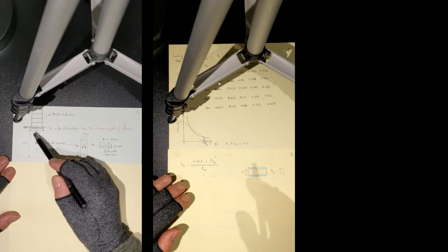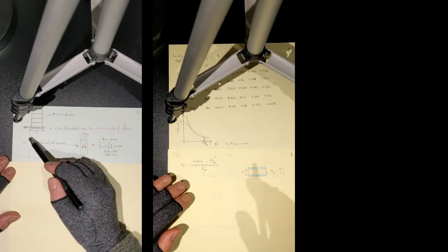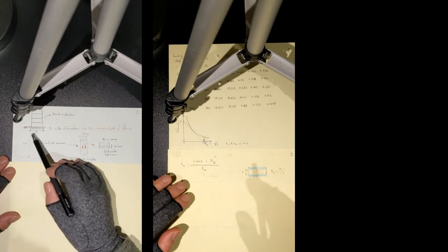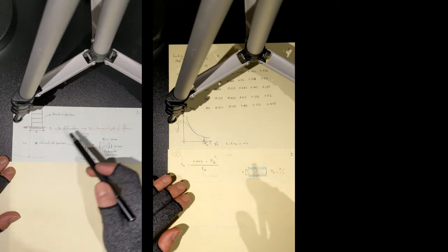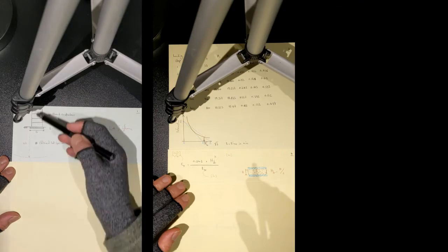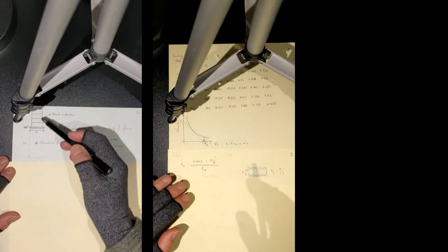But if you have anything within this zone, since this zone is all impacted by the stress state change from construction, then this needs to be studied. So 3 times B is the maximum depth of influence, and this is your zone of influence. Now let's assume that before construction, you know how tall your building is, so you know how much load is going to apply onto the ground, and based on that, next year you will learn how to design the dimensions and type of your foundation.